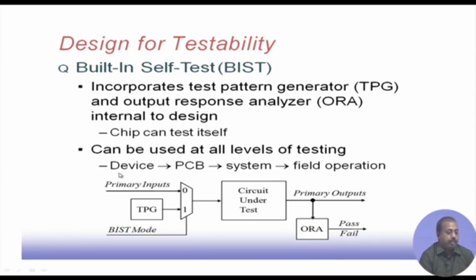So, it can be used at device level, PCB level, system level, or field operation. It is particularly important for field operation, because there I do not have any ATE available. There the circuit itself generates its test patterns and compares responses to detect its health.